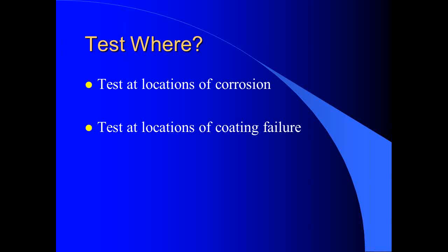If that coating has got a couple of years lifespan and it hasn't failed, wherever the non-failed areas are, chances are there's little to no salt beneath it, or it would have failed. So don't ever waste time testing areas where the coating was good. Always test where the coatings have failed. And also test at weld seams.